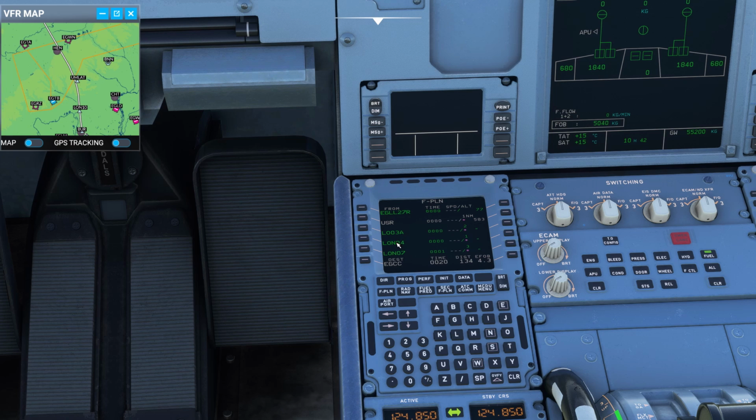Now if you want to look at these waypoints that it's entered, all you do is click the up arrow and it will go down. So you see my next waypoint from there was actually UMLA. By entering the departure, I've already skipped a step that I would have had to do previously. So now I don't have to mess about by entering UMLA.